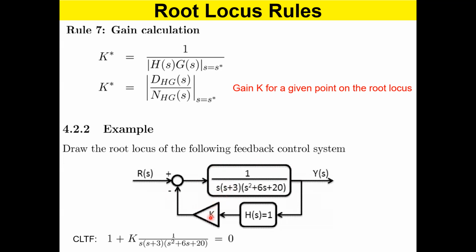Now, when you have some non-zero k, poles are at different points. When you change k, poles move. If there are, let's say, 5-6 poles, it's like 5-6 aircraft in the air. They are moving like an air show, different aircraft moving in different directions. As you increase k, the poles move. And when you increase k to infinity, some of these poles will go to the zeros here, the open loop zeros.